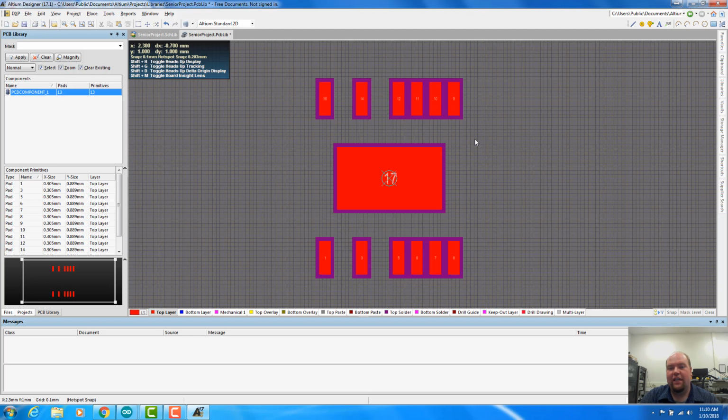So what I like to do is put a pin 1 indicator. Usually a pin 1 indicator is done by a dot, and there will be a dot impression or a dot laser marking on the actual component, and then we'll also have a silkscreen dot on the board. It makes it very easy to place parts.